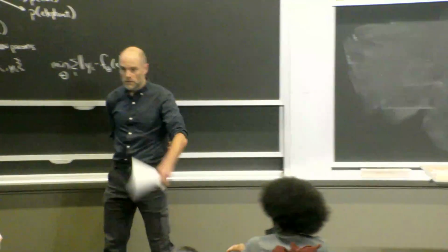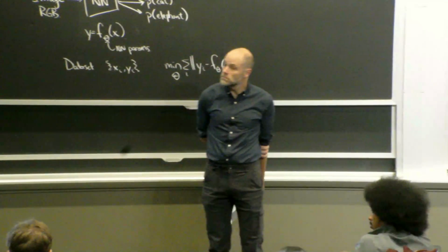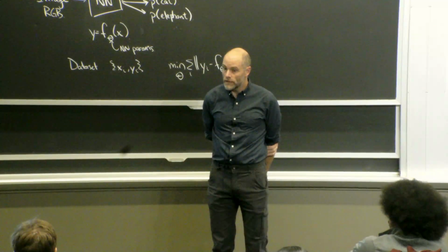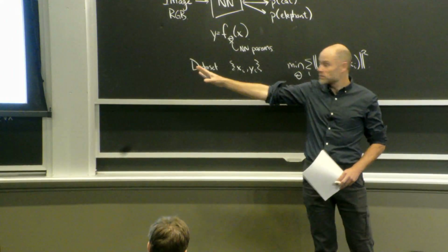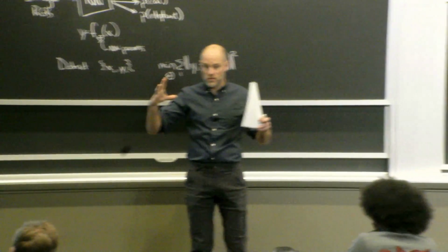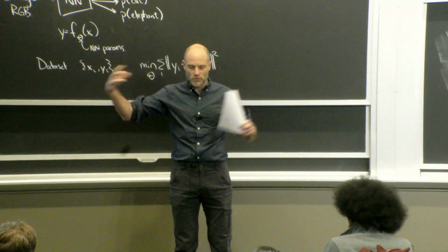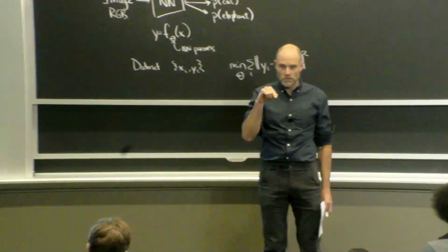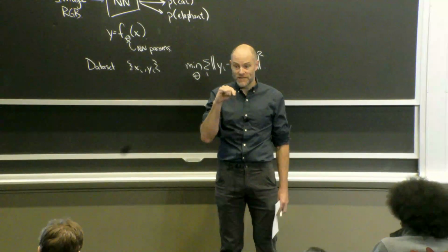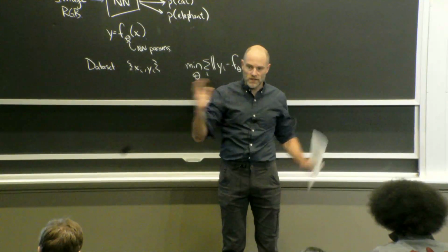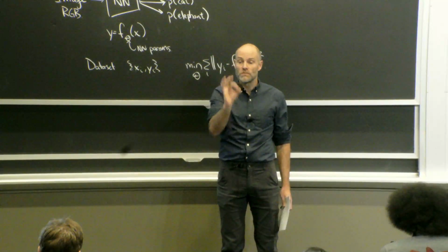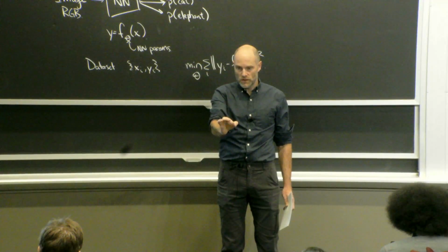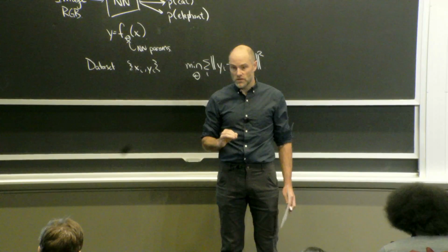Yep. How do you combine segments from different cameras? Yeah. So this is the segmentation right out of the box of a computer vision will be a 2D image segmentation. So you have multiple cameras looking. Each one you label a pixel as being part of the mustard bottle or not. You project that into 3D, and then when you merge your point clouds, the most naive implementation would be you only merge the point clouds that are associated with the mustard bottle into the 3D representation.